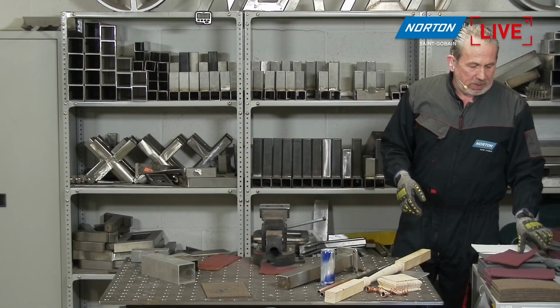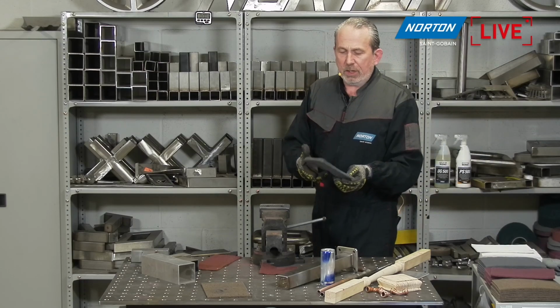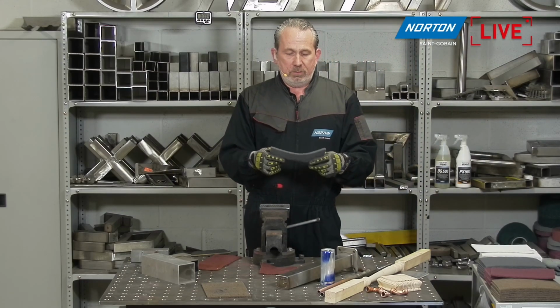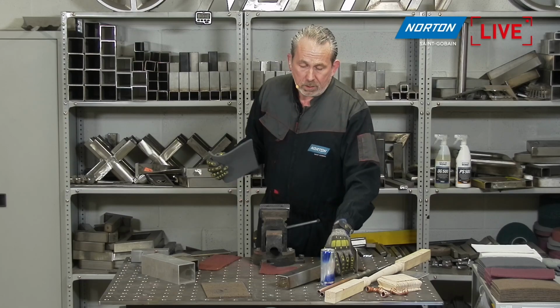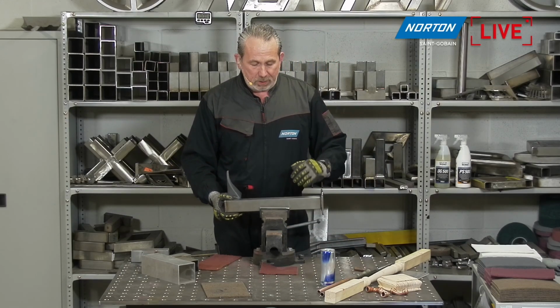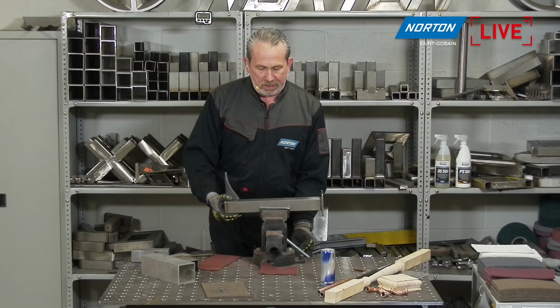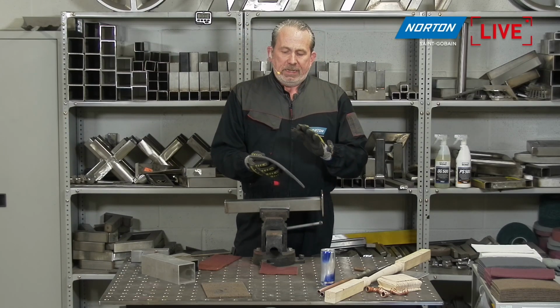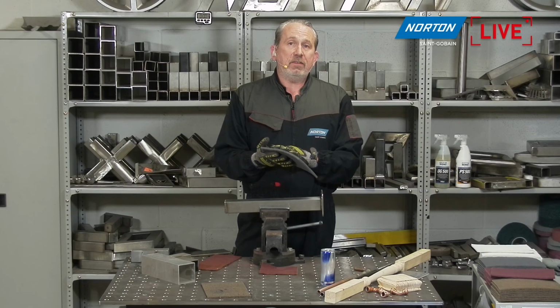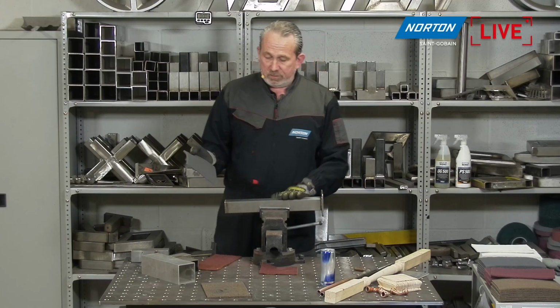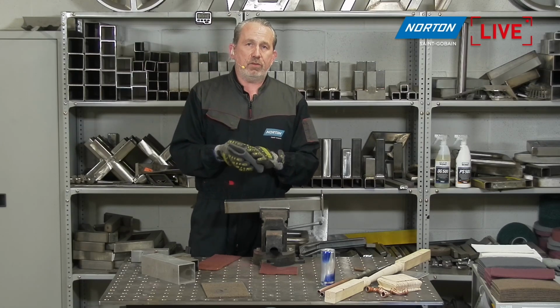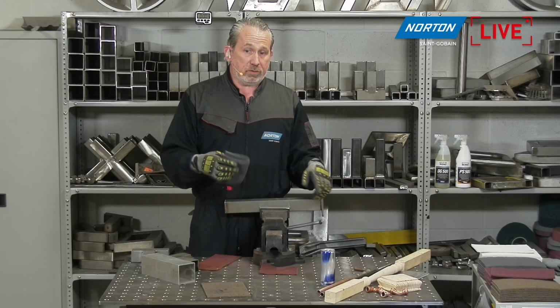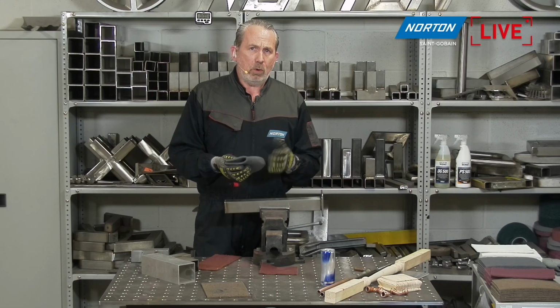Next product we're going to have a look at is our silicon carbide very fine product. Okay, we can bring back the steel balustrade we had earlier and give this more of a finish, because this is more for final finishing. Inside here we've got an ultra-fine silicon carbide grain. On stainless steel that works really nicely at giving us a much brighter finish than the aluminium oxide grain, which are in all these other products. It'll give a much brighter finish on stainless, so it just pops out a little bit more.